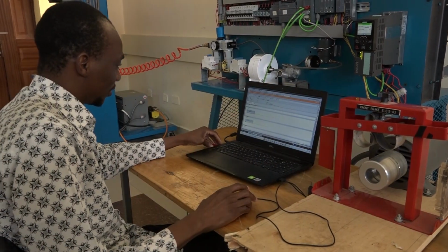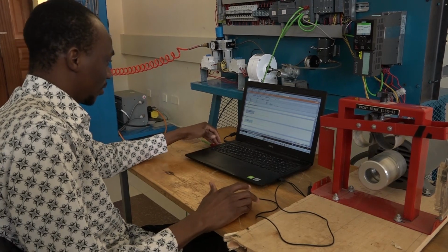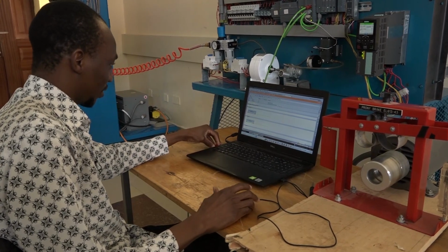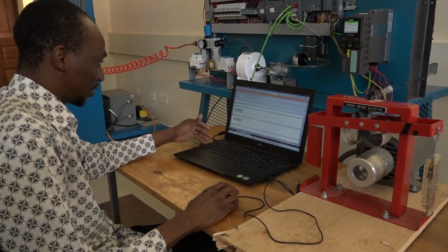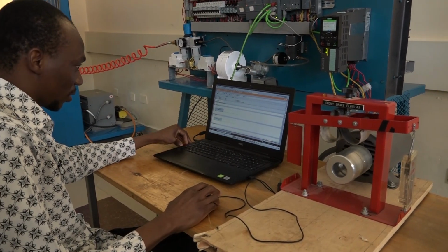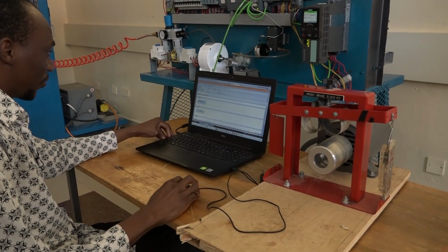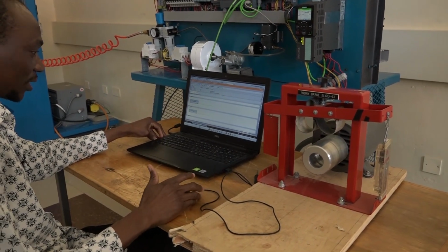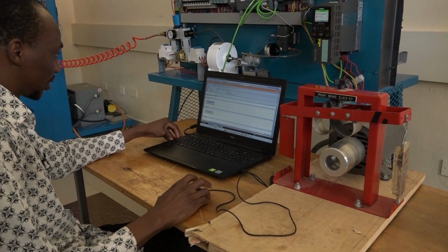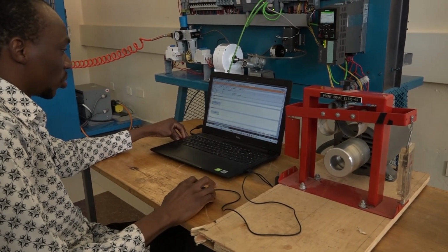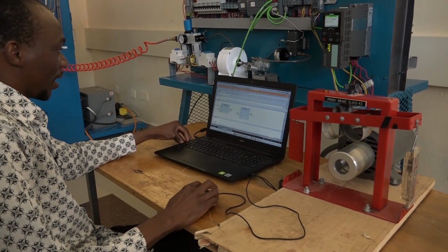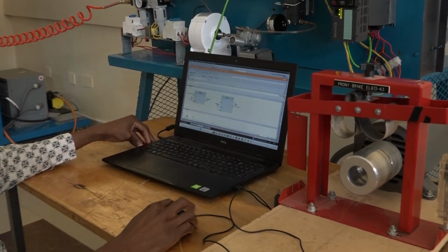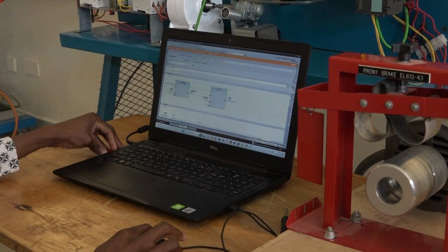Thank you. The PLC program has been done in the TIA Portal environment, TIA Portal V17. We have 3 steps in the TIA Portal PLC. The first step is the compressed air compression stage, which is monitored by the drive and motor. If I open it, I have the NORM_X scaling, to convert that signal to a real value.